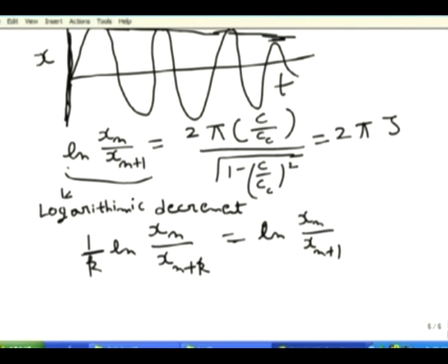So, it is better to measure the logarithmic decrement based on the measurement of first, say, one peak, and after that 4-5 peaks ahead. So, this is about the logarithmic decrement. Here we are assuming the viscous damping.